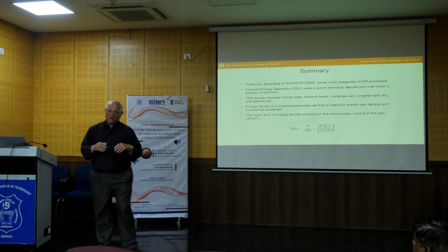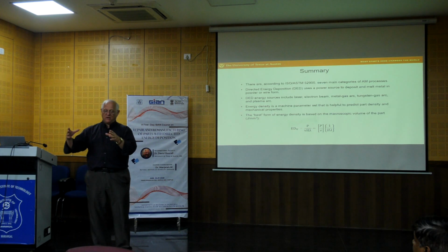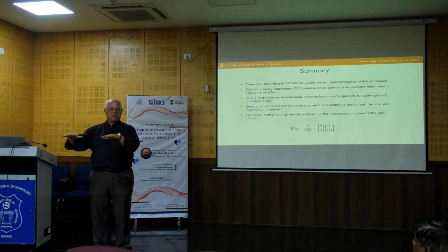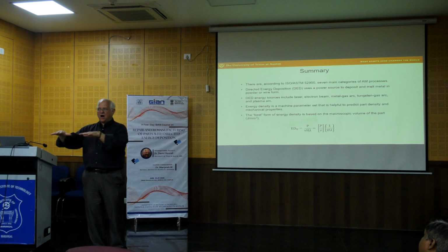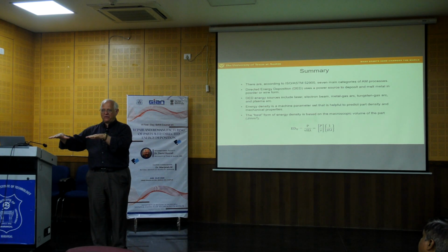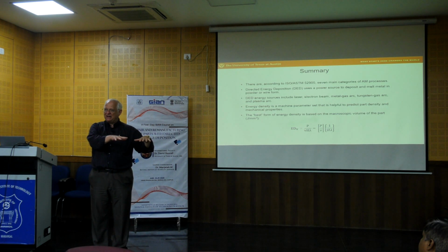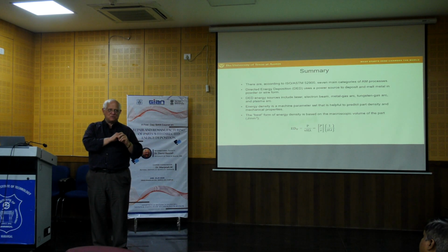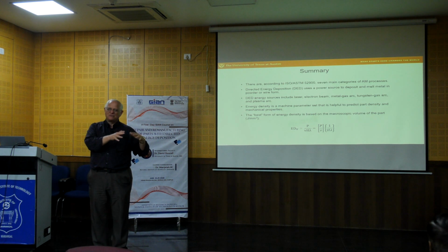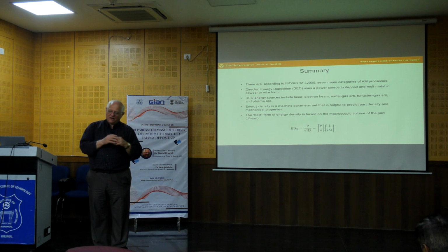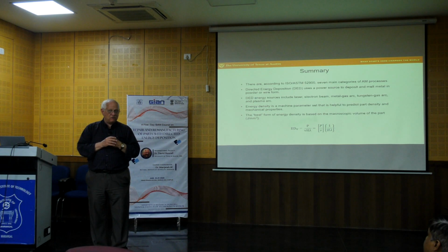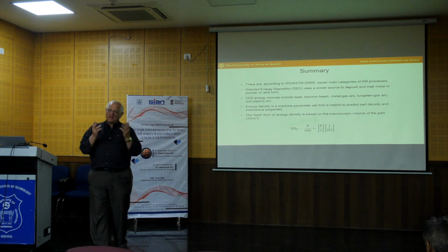And what it is, it's a technology. There's a company out producing parts this way. But what they do is they basically spread powder away from the machine onto a layer. They create a layer of powder, and then that layer is maybe lightly bound, but then it slides into the machine and it's processed. So it's really not sheet because there's no sheet involved. It's not powder bed because there's not really a powder bed either. And so, at least in our discussions so far, I think the name would be powder lamination as an eighth process. But again, the jury's still out.